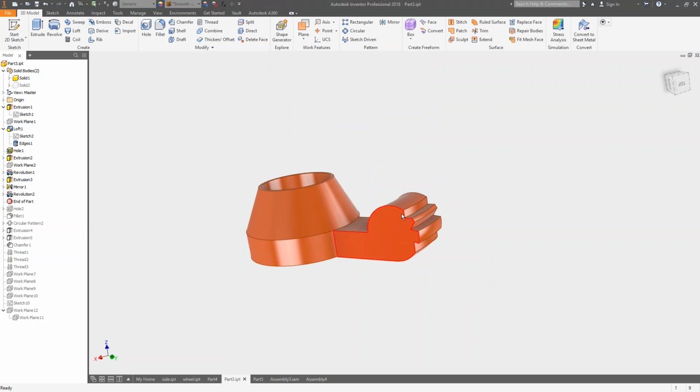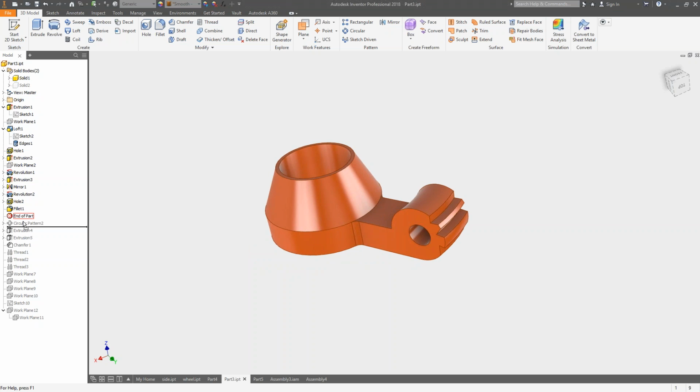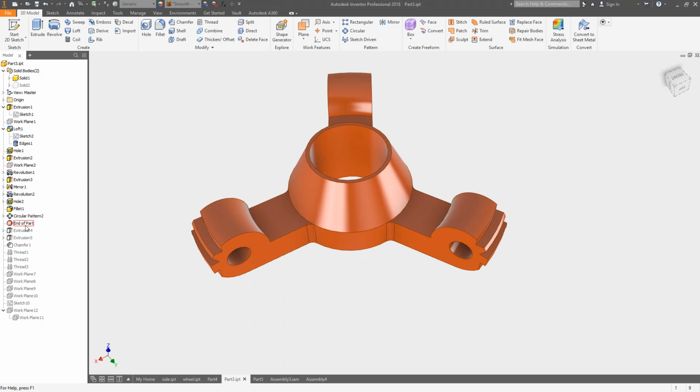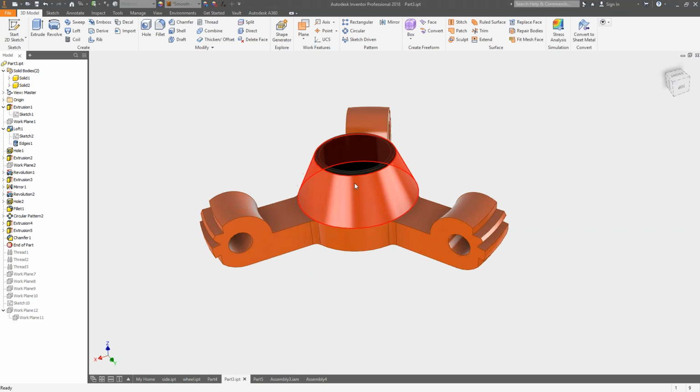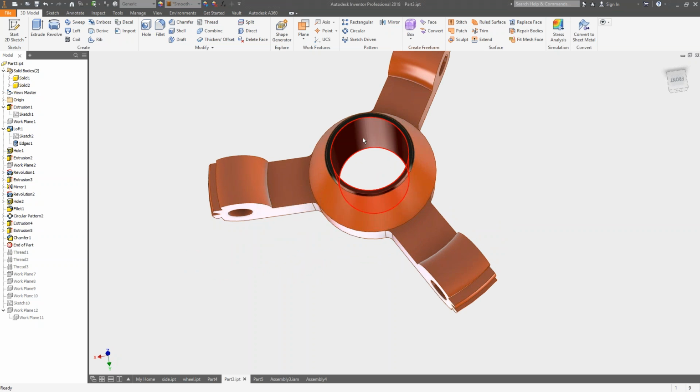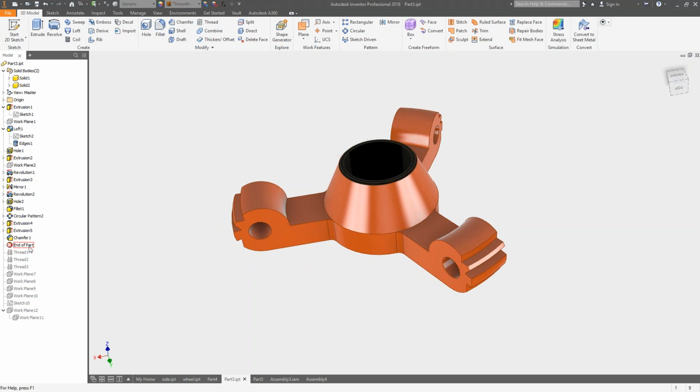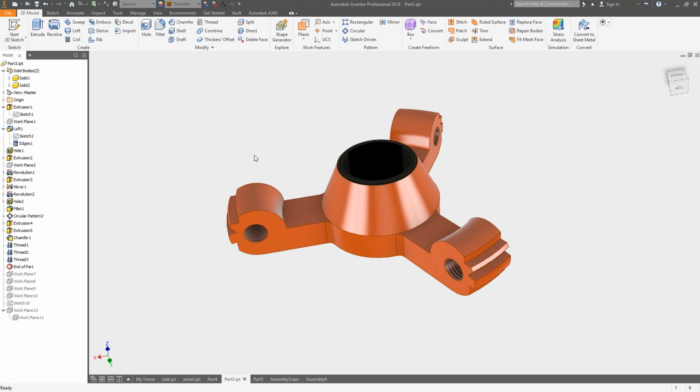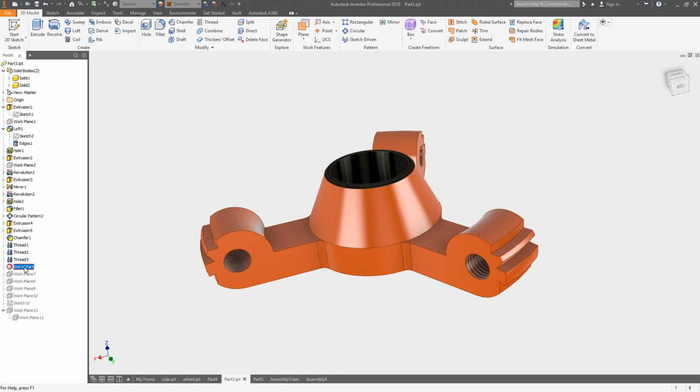I then added a revolve on the end to get the stops. This is actually a little metal component in a tripod. So if you kind of think the legs go down, those are the little locking nubs. I punched a hole. I started doing some fancy filleting, did a pattern, added a couple of chamfers. I added my multi-body part there, so my second solid. I threw in a few cosmetic threads, and that's it.